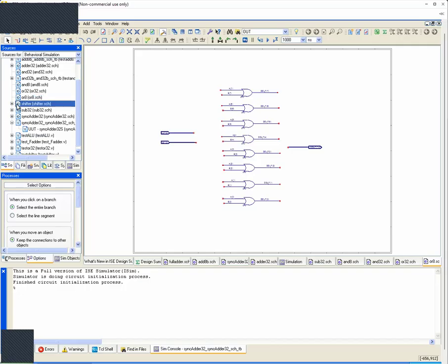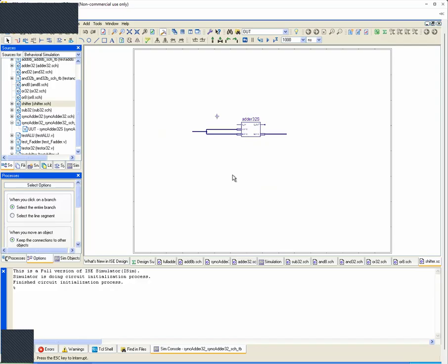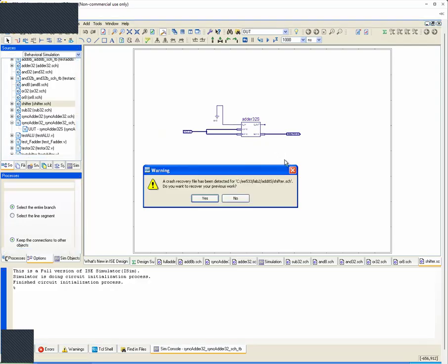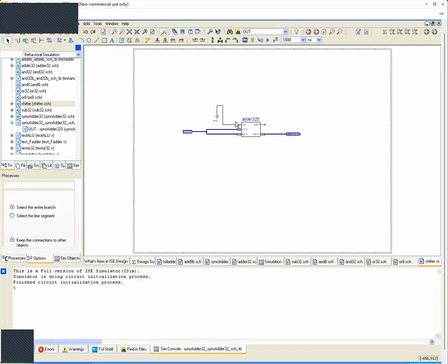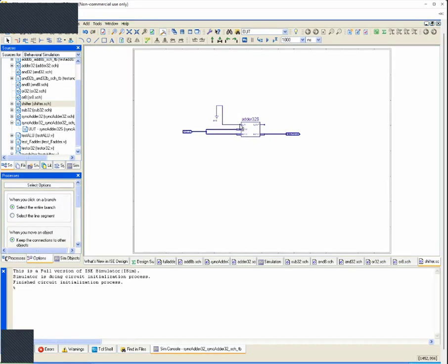And using the full adder itself, I have built the shifters, like the 1-bit left shifter. If we give the same input to both inputs of the adder, the output will be 2A, which is nothing but the 1-bit left shifted value of A. So this circuit will give a left shifted value of A by 1 bit.